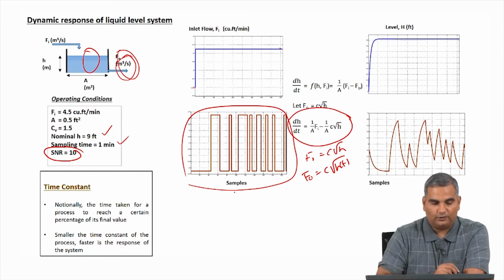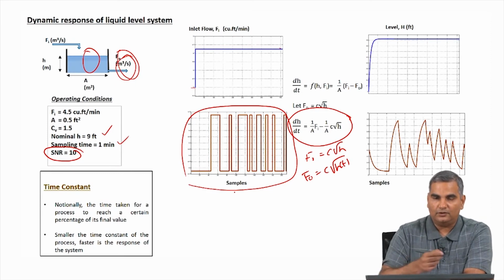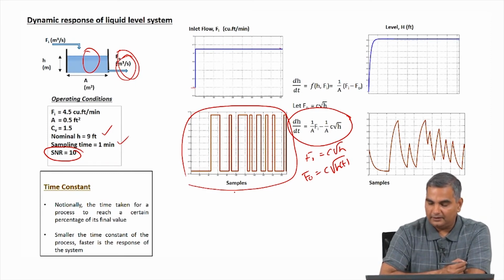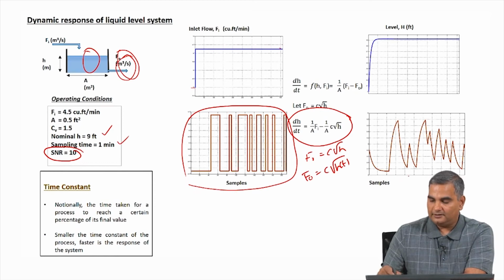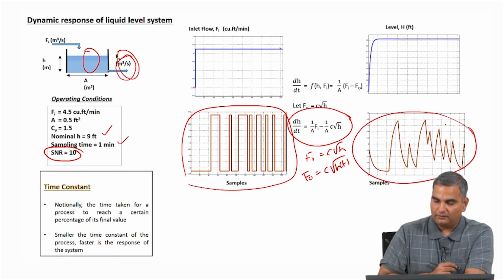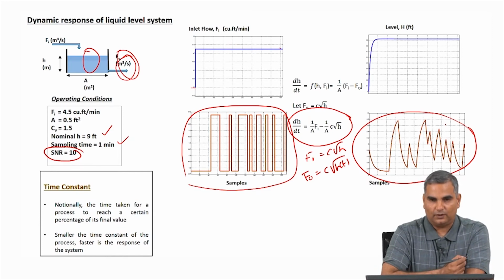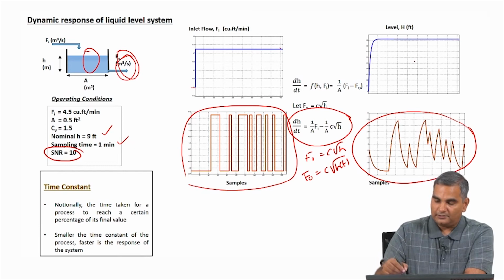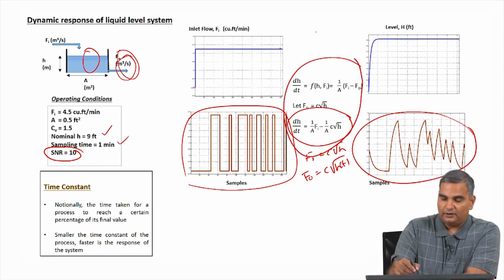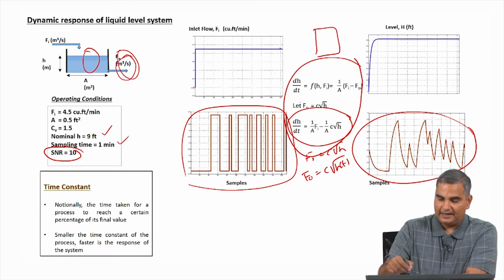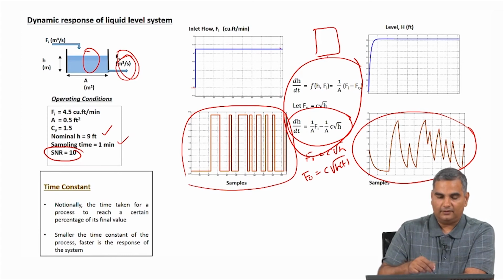One thing is you can do the experiment, the other thing is actually you can use the model that has already been built and then say this is how this is going to look. So, this is the output of the model for the height, and actually you could do the experiment and verify this is true or not. And these plots have been generated using this equation. So, really physically if you think of it as a tank here where the input changes and the height changes, the tank is being represented by these equations.